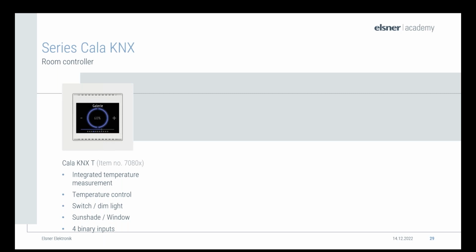I just saw there was a question. All right, thank you very much for the question. It's quite an interesting one. So how do you recommend the setup when using two-point control? So actually, you always want to use two-point control if you have 2 different sources of heating. So you have 2 different heating systems. If you remember the example of the bathroom, you have a sort of slow heating system that takes a while to adjust the room temperature, but is able to keep it very steady. For example, the underfloor heating. And you have some sort of more rapid heating system like a wall heater, for example. That is when you should always go for two-point control.